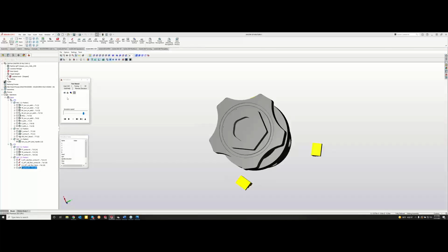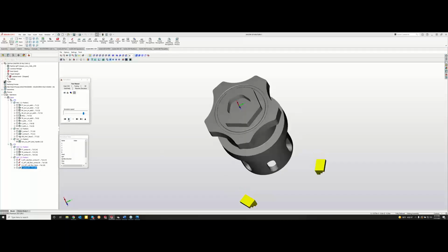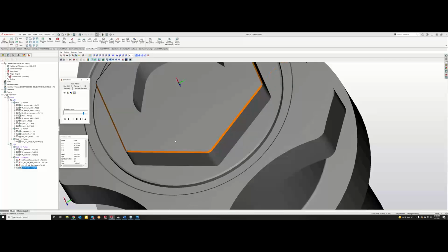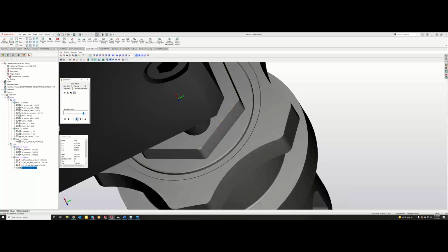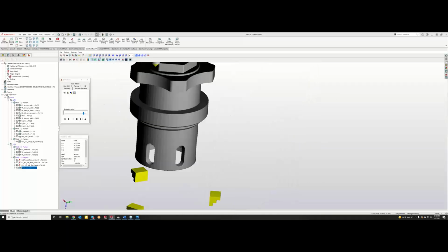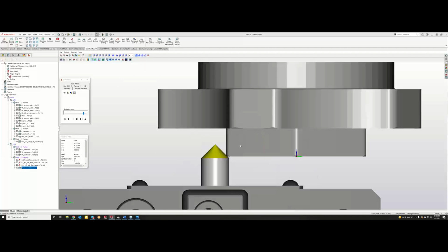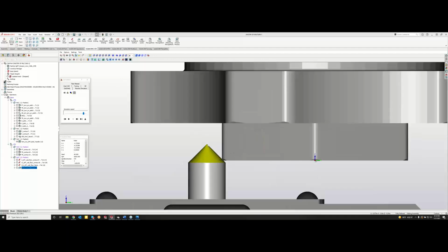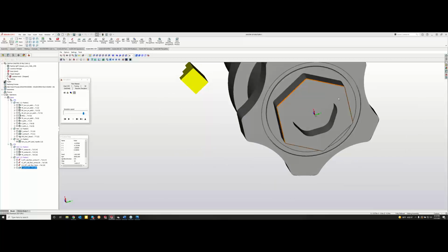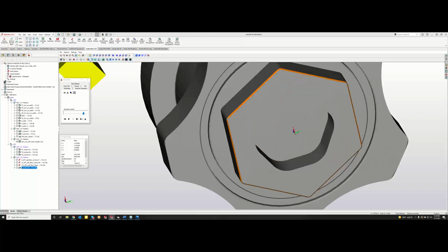Solid verify. Now that number that I specified there for that 200 thou does not determine how deep this chamfer is. It only determines how deep we're using of that tool. So if I get another side shot here, now I can see instead of working on the tip of my spot drill, I'm working more on the outer diameter of that spot drill. Okay. So let's go ahead and play this through here, and we'll make sure we're up to size.